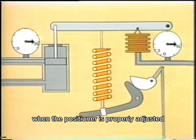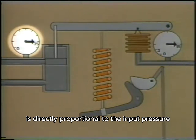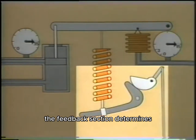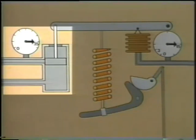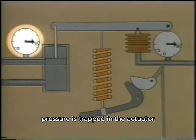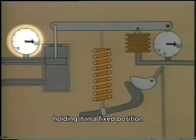When the positioner is properly adjusted, the resulting output pressure is directly proportional to the input pressure. The feedback section determines when the actuator is in the correct position and closes the pilot valve to shut off the flow of air. Pressure is trapped in the actuator, holding it in a fixed position.